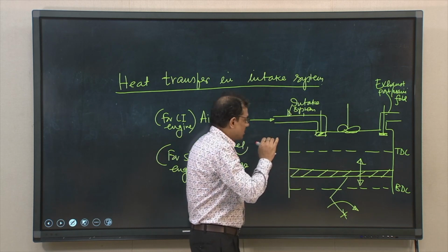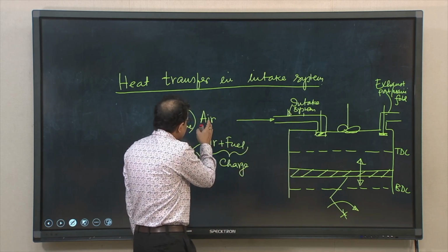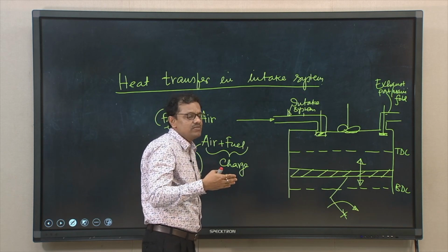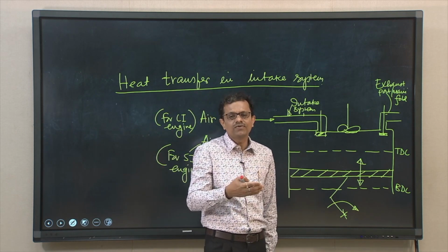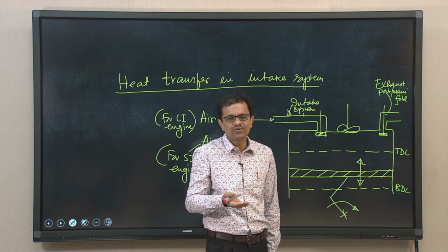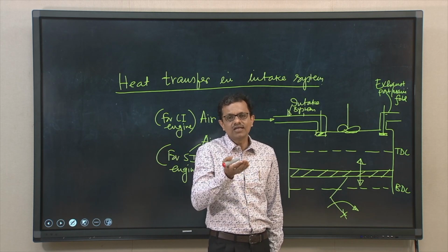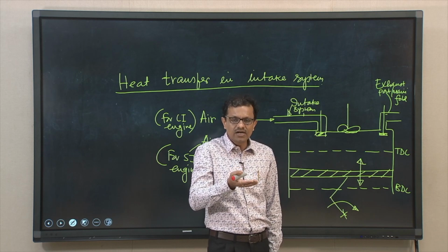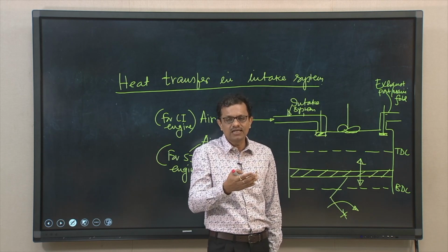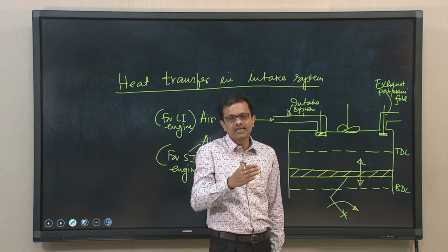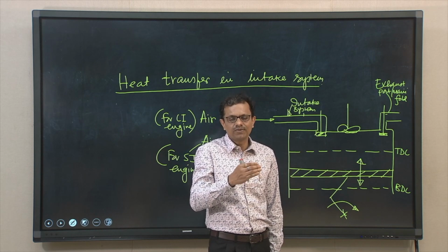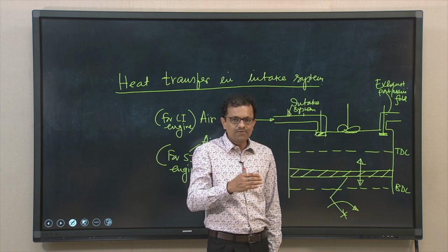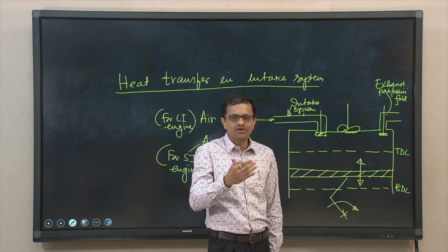Now, the question is, when the incoming air or incoming charge temperature increases, this again sometimes becomes favorable for the combustion, because if we can increase the preheating of air or preheating of charge... If we have a proper design, to some extent preheating of the incoming air or charge is necessary.